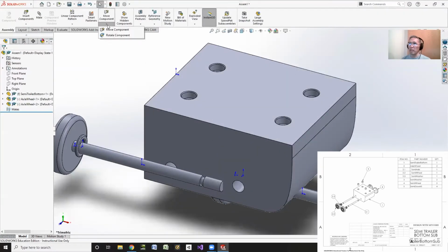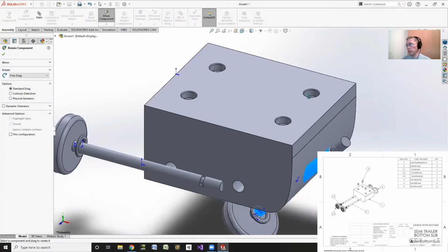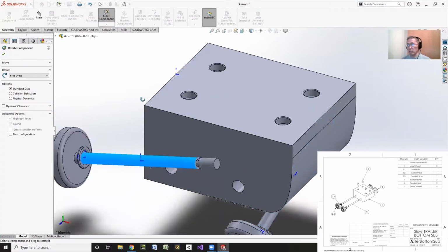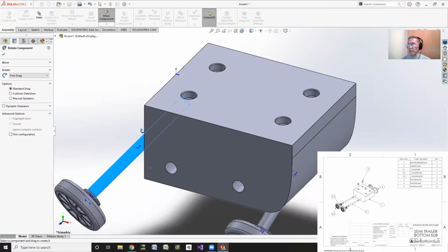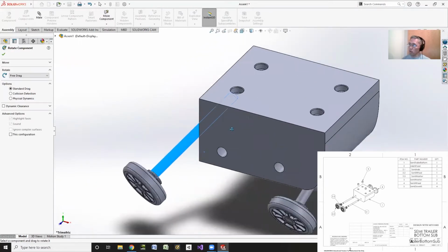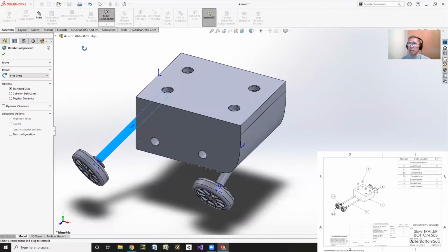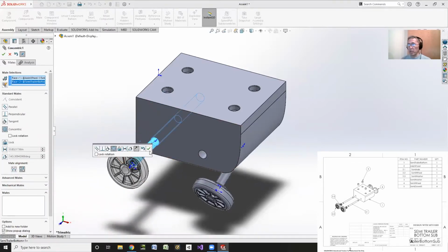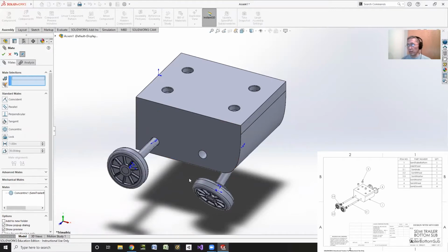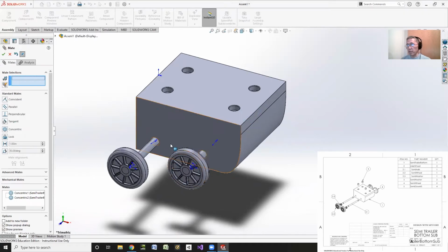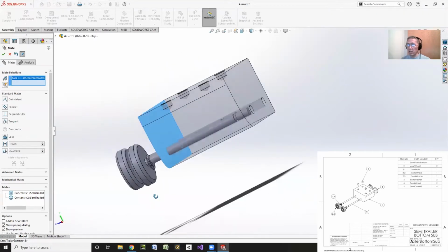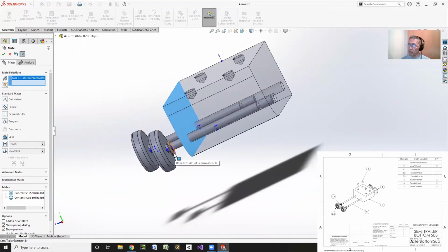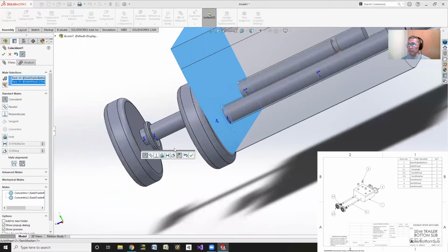All right, now I'll go ahead and rotate the components so they look a little bit closer to what we want. Same thing with this one, just a little closer. And then I'll zoom out a little bit. We'll control wheels and middle mouse. And then I'll go ahead and mate them. So the mate I'm going to have is this cylinder, which I already selected, and that cylinder there. And we want them concentric, which they are. I'll have to check. I will rotate around a little. Actually, I'll just grab this cylinder and that cylinder, and we'll make them concentric as well. And I'll grab this face, and let's grab the near face there. Grab that face there. That makes them coincident.